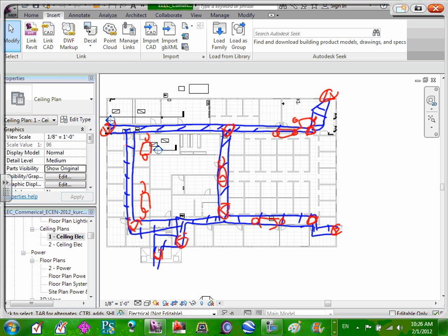And we're using bug eyes. The question came up, Nick, you asked that one: how often do you use a fixture like this with battery backup versus bug eyes? Architects like it because then you don't have a bug eye sitting on the wall. They work the same and last about the same amount of time, but a lot of times they get forgotten, because you don't physically see it.